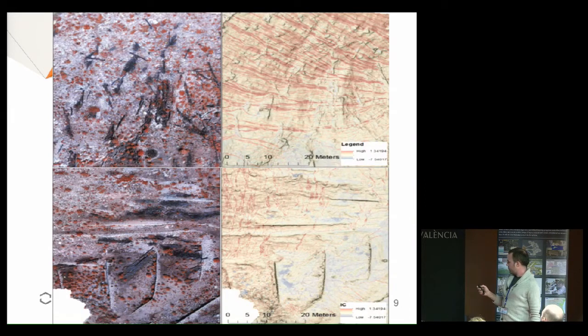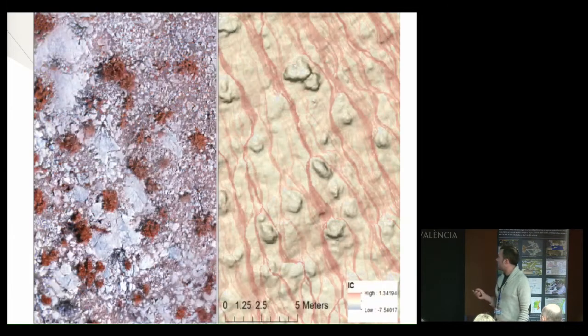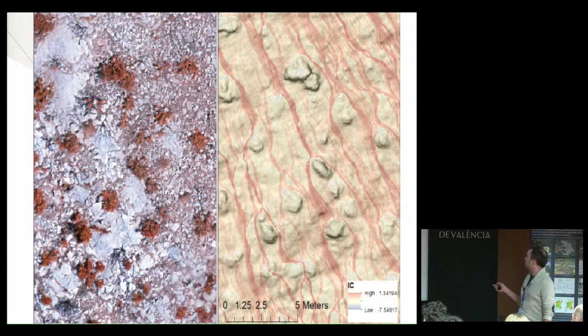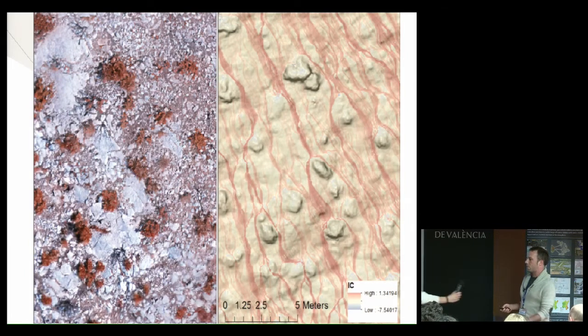I'm not sure if you can see, but all these will be the potential higher flows along the catchment. Then you can see obstacles, which are basically the log barriers. In Tramontana, the agricultural terraces, abandoned 50 or 60 years ago, are really important. You can see that in the area where the terracing was done, the flows are much less important. We are also studying how the recovery of vegetation will affect the runoff and the potential erosion. Here you can see the vegetation in red, and how this vegetation is affecting the flow.